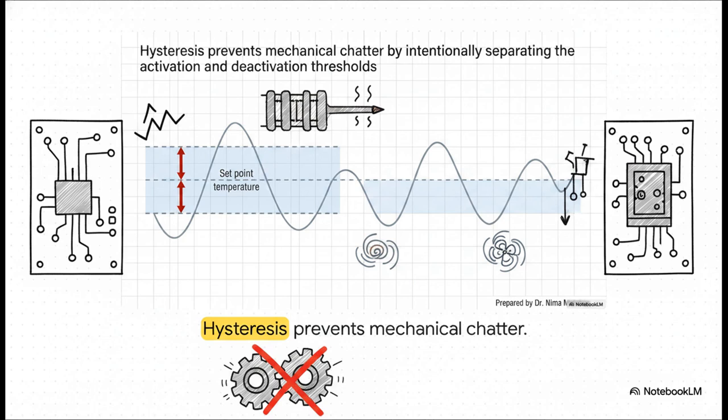And this brilliantly illustrates exactly why that oscillation has to happen. It's a concept called hysteresis. You see, that deadband isn't some flaw in the system, it's actually an intentional, highly necessary design choice. The system relies on two distinct thresholds, an upper limit and a lower limit. If the switching threshold was just a single, razor-thin line exactly at the set point, the relay would just rapidly and violently switch on and off as the temperature hovered on that exact line. Engineers call that chatter, and it will destroy a system fast.